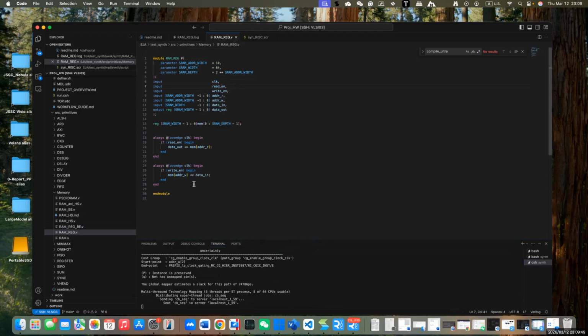For this you need the RAM to replace the large register file, because it's a large overhead for area and for the synthesis tool. Because the number of data paths is this many, but if you replace this with the RAM, the data path is only one.